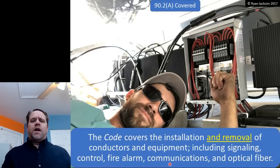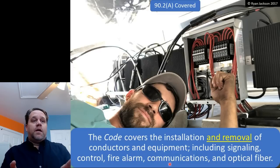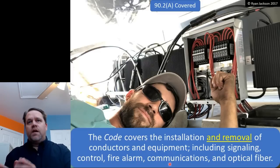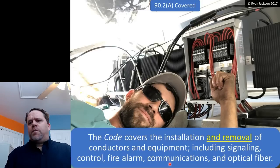If I built a building in 1950 and it complied with whatever code was adopted at the time, then that building remains compliant to this day. If I go in and change stuff, then the changes that I make, the installations that I make, need to comply with today's code, because the code again covers what you install. Once it's installed, it's compliant, and it remains compliant until you mess with it, until you make another installation. Because again, installations have to comply with the code, but the code doesn't cover maintenance, it doesn't cover upkeep, it doesn't cover usage. You don't have to update your building every 3 years when the NEC is updated.